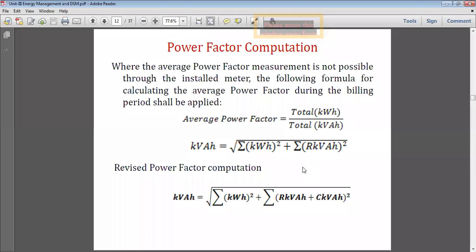The current will be minimum only when the power factor is unity. At the same time, when the lagging kVAR is smaller, that is, when there is a deficit of lagging kVAR, the voltage decreases, so the voltage profile decreases. Whereas if there is a surplus of reactive power, that is the capacitive one, then the terminal voltage increases. So if you are not maintaining the power factor at unity, the voltage may increase or decrease because of the lagging kVAR or leading kVAR.